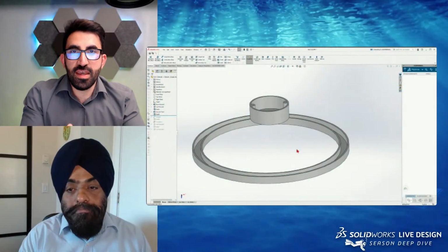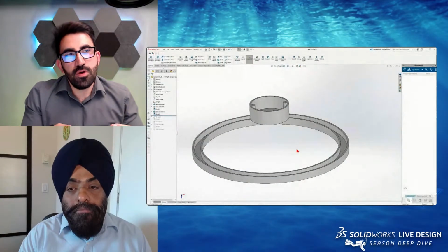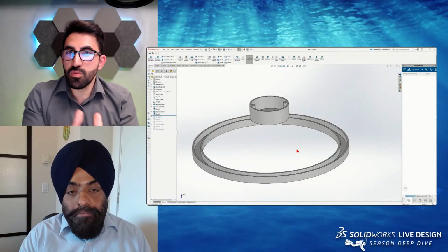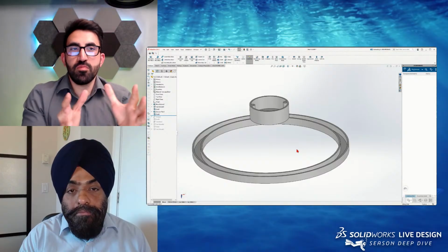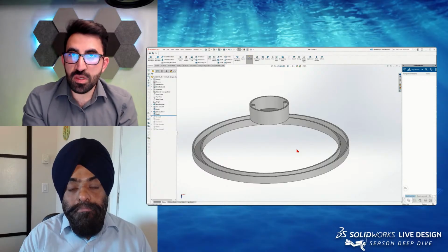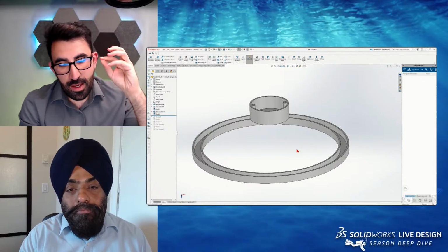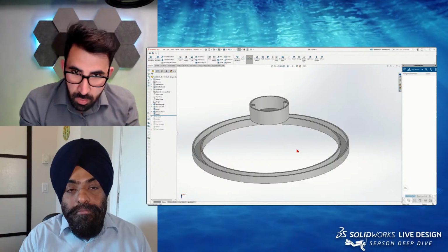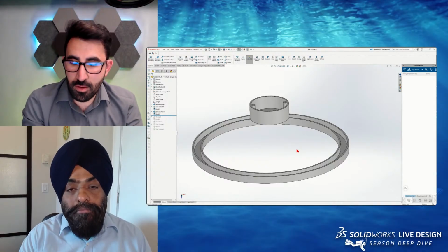If you are creating a system made of multiple components that need to be assembled together, you need to take into account, are they able to assemble this easily and dismantle it again, or it just works inside SolidWorks because it's virtual? So there is a difference. In this case, we are going to manufacture this. This is being designed for manufacturing. So we are taking the actual physical products that we want to insert or connect to this component into account.